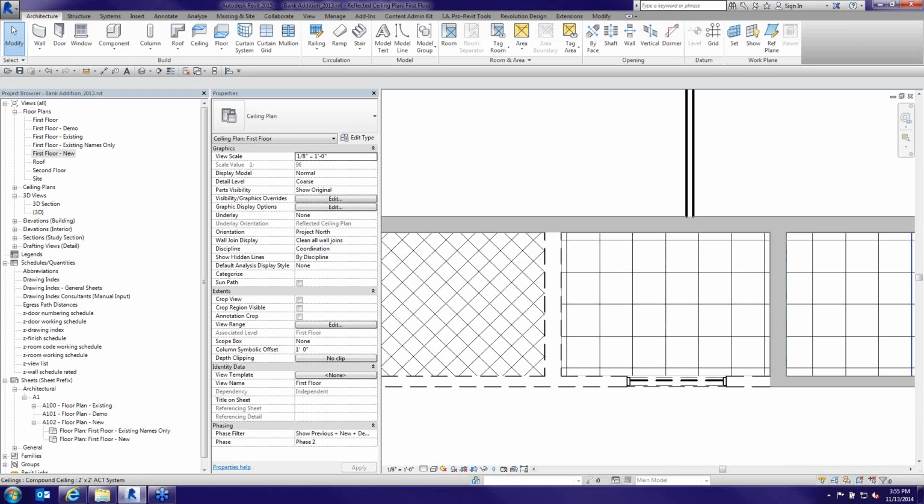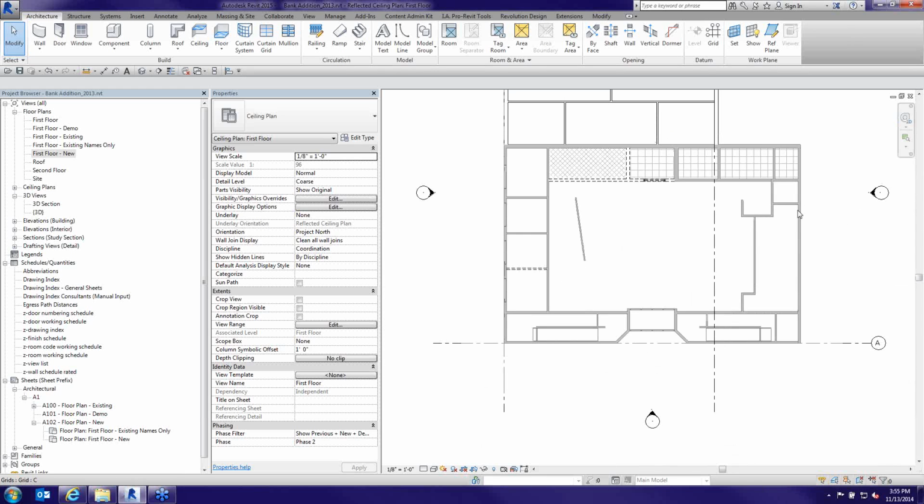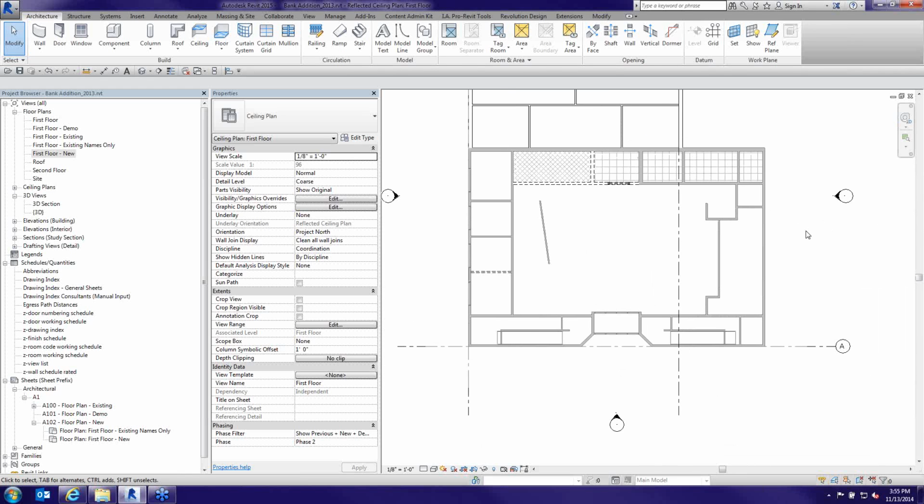I use phasing as it's intended, as phasing. I currently have a project right now where there's physically 9 construction phases, and so in the project there are 9, well 10 because we have existing in this case. So there's 9 remodel phases plus the original construction. So we go through and there's, you know, one project, we actually had 9 different Revit buildings. It was like the 1920 construction on this museum, the 1940 construction, the 1960 construction.